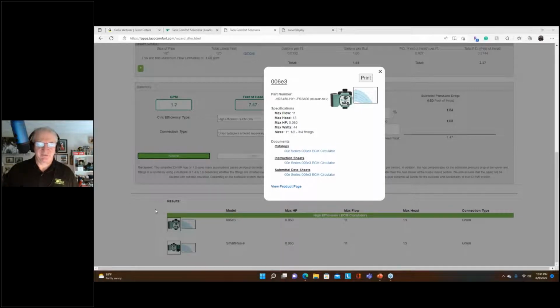If the fixture was open, could it conceivably happen? I don't think so, because there's no pressure differential on that side. We're not creating a pressure differential on the cold water side to suck flow through the faucet and into the cold water line, into the hot water line. I don't see that happening. I don't think that's possible. So good. Let me know if I answered your question.